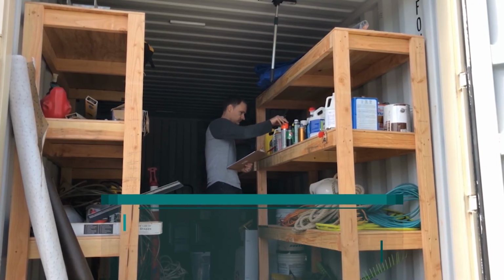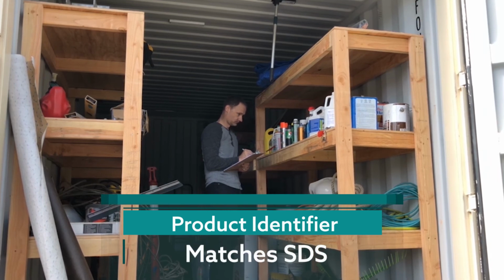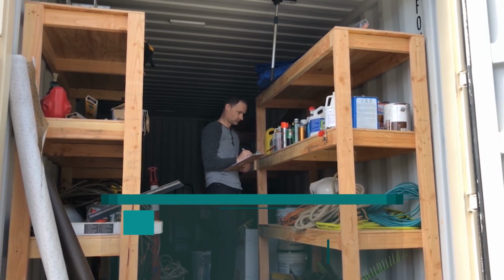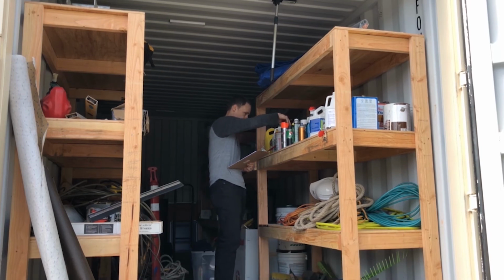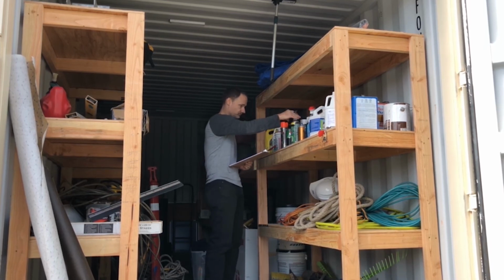If it sounds like it's written by lawyers or for lawyers, it's probably not the most effective program. The first step to writing a hazard communication program is you have to take a chemical inventory. A chemical inventory is simply a record of all the chemicals that you have on site. When you're writing down the chemical inventory, you need to make sure that you write down the product identifier on the label. The product identifier must be on the label, and it also must match the product identifier on the safety data sheet so that in the future when employees are trying to cross-reference the two, they'll all match.